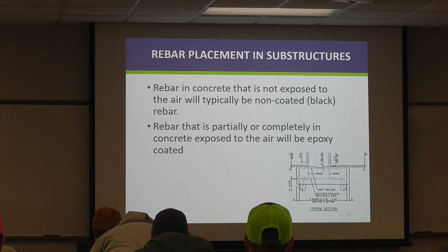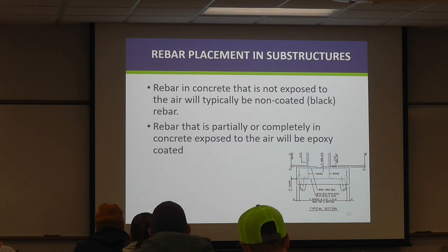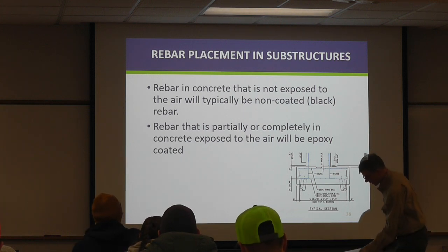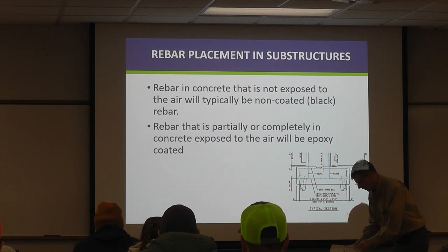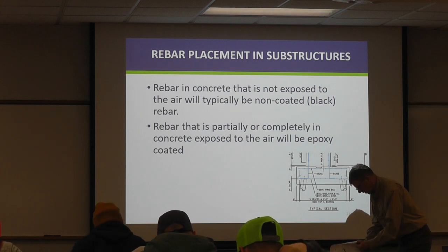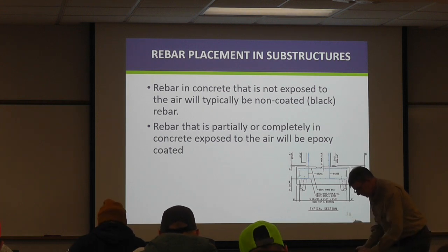All right, how about rebar placement in the substructure? So Mark brought us through rebar. Rebar that is in concrete that is not exposed to air will typically be non-coated or black reinforcement bars. So on this sketch, what bar designations, or bar numbers I should say, are only in the footing for the south abutment?